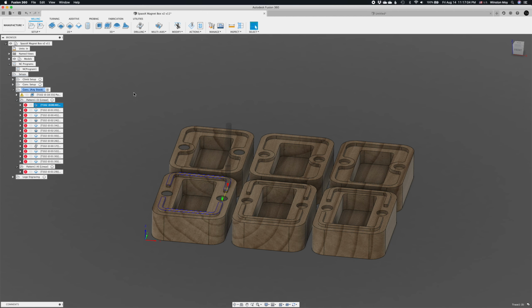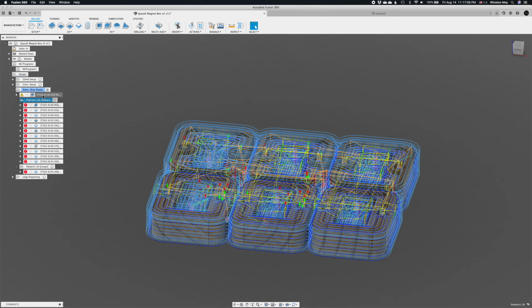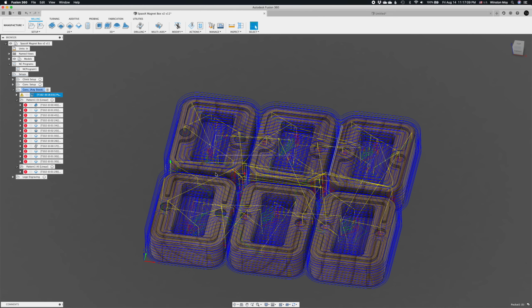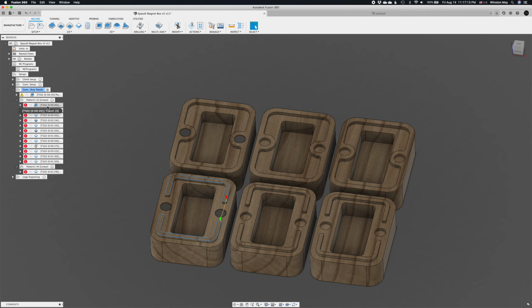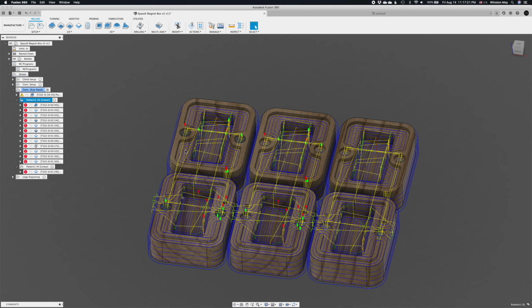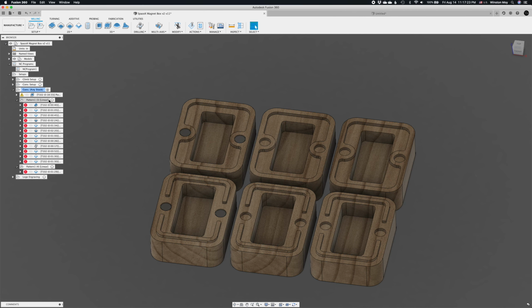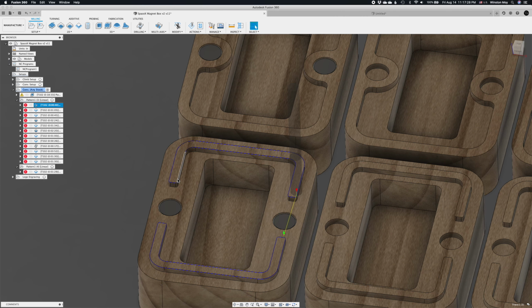So the next toolpath on this is in a pattern. Since the roughing toolpath will just target all the models in the project, this one I'm targeting contours, and I don't want to select them 3 different times, so I'm just patterning out one set of toolpaths for one box across all 3. Here, I'm doing a trace operation on the perimeter of this lip.